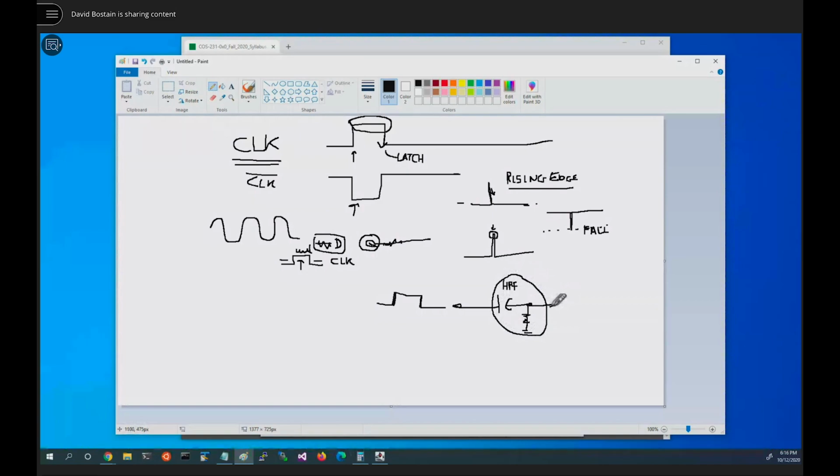Out of this, on this side of the capacitor, we're going to see a signal going up. I'm drawing it on the wire here, and then a signal going down. But because this signal is relative to ground, we'll only see the rising period. We'll see it every time there's a rising event here. We'll see one of these pulses over here. And if we use this as the clock for a flip-flop, then we're truly using just this little tiny edge piece or level piece right there, which is on the edge, in order to capture the signal, which is exactly what we need to do.